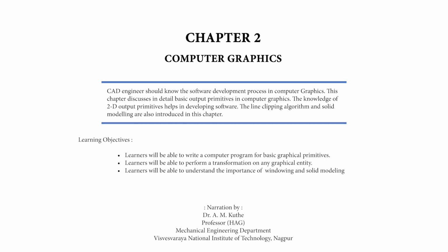Number 3. Intersection of two solid surfaces can easily be created in solid modeling, which is not possible in wireframe modeling unless the point of intersection of the curves representing the surfaces are separately computed, which is a cumbersome and time-consuming process, even then leading to ambiguity and confusion.